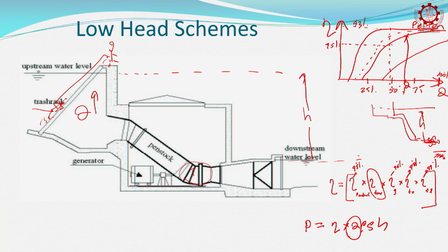These curves you can get from the manufacturers. When you are buying equipment, you can ask what the efficiency curve is, or there are typical efficiency curves from long experience. If you search the net for turbine efficiencies, you will see a set of curves like this, though the manufacturer will give you the exact values, the top values.